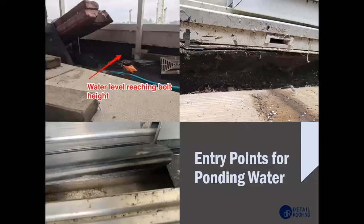So again, if you do have a situation like this where the water is ponding and rising above certain levels, there are various ways that the water can enter, whether it's along the side of the stripping membrane or any unsealed penetrations or railing posts, if there's any inadequate waterproofing along the doorway, or if it's getting, again, up above the doorway or into the metal flashing details along the side, this can, of course, cause leak issues.